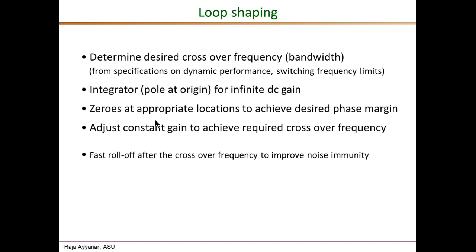And in most cases, for example, if your objective is to control the output voltage, when we sense output voltage, we know that there is going to be a high frequency switching frequency ripple, and we may want to attenuate the magnitude of the switching frequency ripple when it enters the feedback controller. So very often we will be required to have a high frequency pole below the switching frequency, so that it provides some attenuation to the high frequency ripple contained in the output voltage or the inductor current, whatever we are sensing.